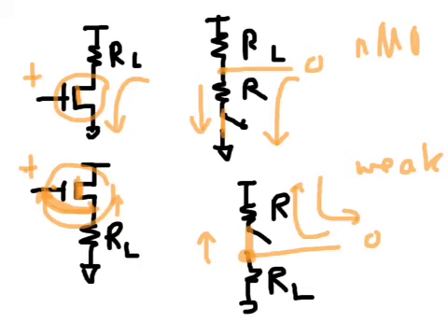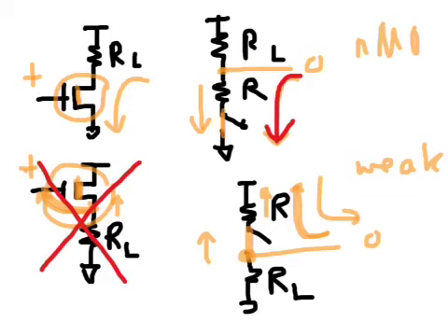This is analogous to a situation where, as this pull-up is happening, the resistance is getting larger and larger, which then slows the pull-up. And therefore, NMOSFETs are typically used only as strong pull-down networks, but not really as a pull-up network.